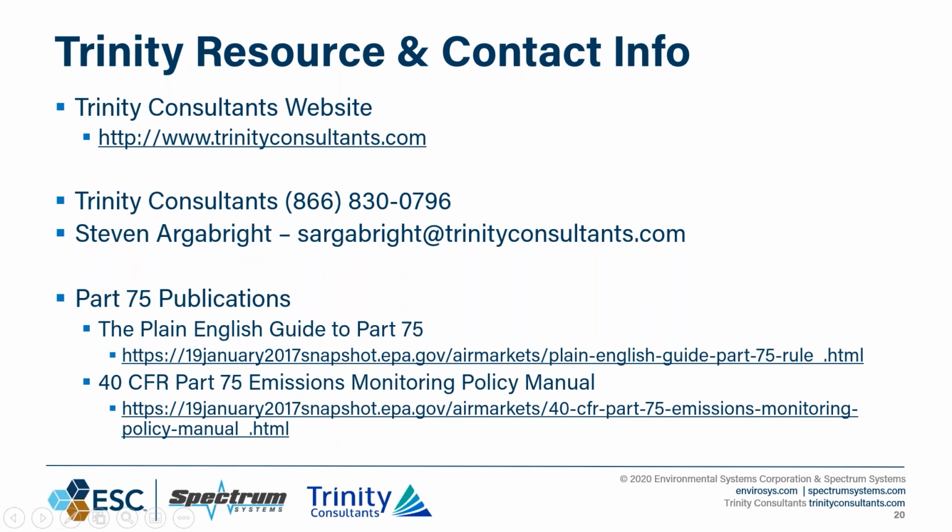And we've got a comment here about CEMS tech data entry into the log. If you do have an electronic log system, encourage your CEMS techs to do the data entry themselves. They know best. They're the ones that are out there touching the equipment. They know what the terminology is. And encourage them to do it real time. Sometimes that's not possible because CEMS is an outside job. You're going to be going into the shack, doing your maintenance, but you need to take that data back somehow into the electronic logbooks. There's a couple of ways to solve that. You can actually have the electronic logbooks in the CEMS shack, add another computer station there so it's ease of use, or make sure they take notes and bring it back to the control room.